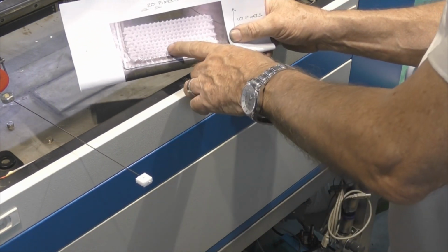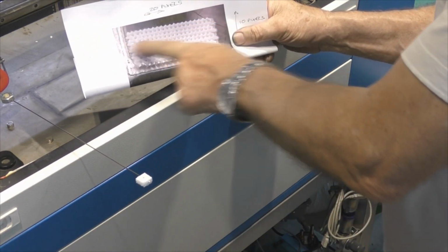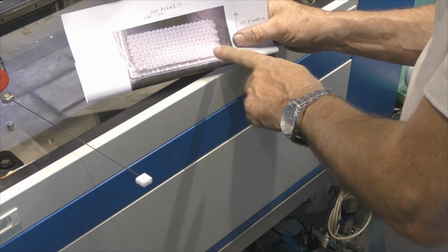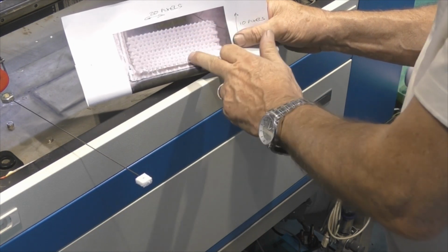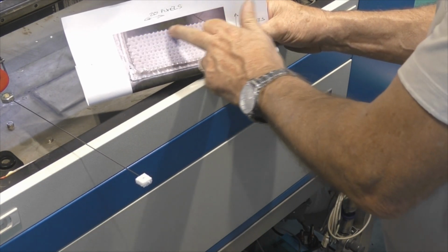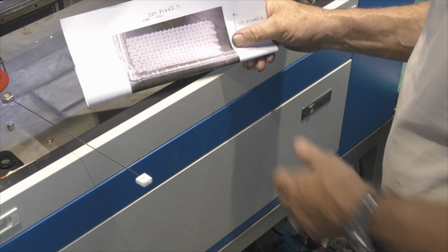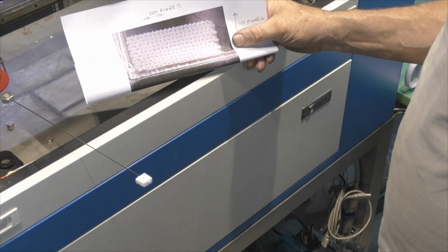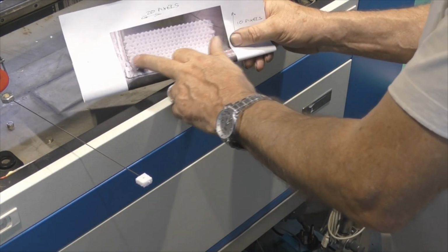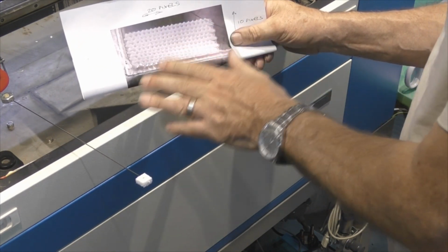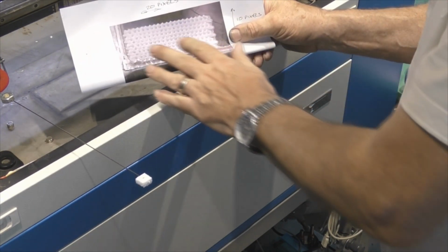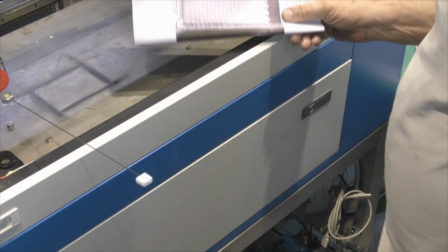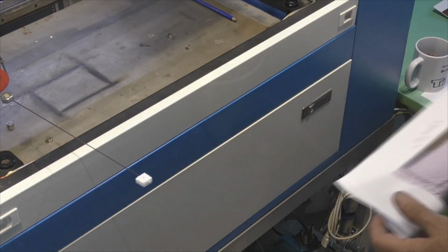I think we're going to have to rely more on the results in acrylic, because these do not tell lies, these are completely repeatable. So all I've got to do is first of all repeat this test to make sure that I can see my pixels. They're not really pixels, but see if I can see this pattern of dots at 50 millimeters a second. If I can, then I know that I've got something that's completely repeatable on this machine. And when I make a change, if I see a change to this result, well, you know, we know that we've definitely affected the performance of the machine.